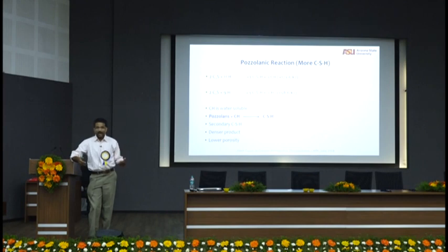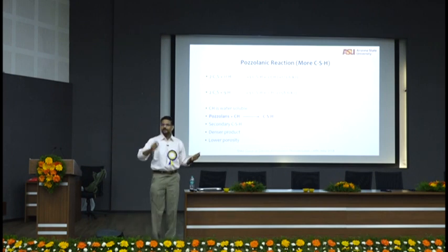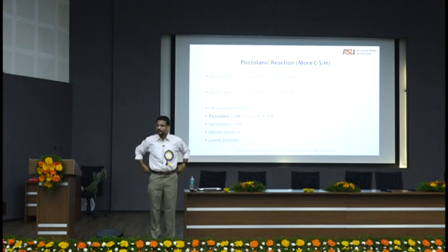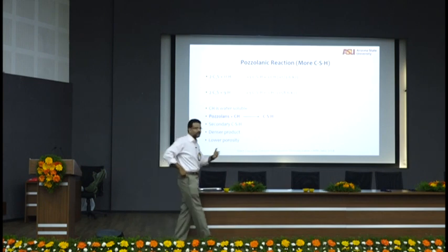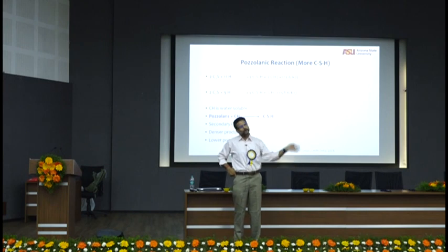You see the argument? And then if your steel is sitting there just relying on the pH that the concrete provides, good luck. And how many of you have seen steel that is put in any concrete that is not rusted? What's the color of steel when you put in concrete? You see any local construction? Brown, right? Unless you coat the steel with epoxy, yeah, then you have an argument. Or I'm saying, oh, I have galvanized steel, I want to protect my galvanized. Yes, you have a point. But anytime we do here, you have corroded 15% of the surface area of steel, and even then the whole thing stands up pretty well, and then you're complaining about, oh, calcium hydroxide is a problem now.